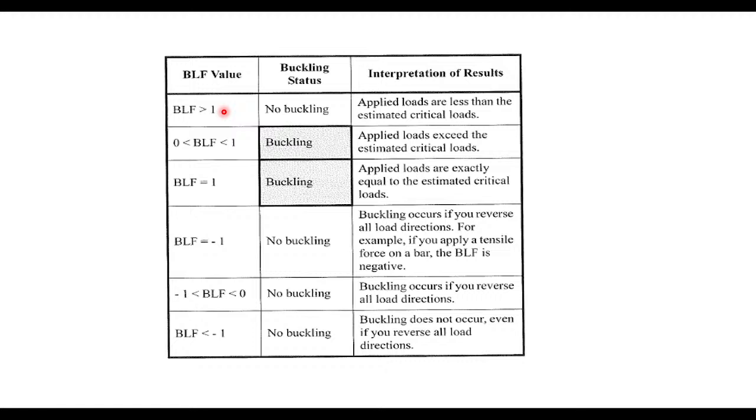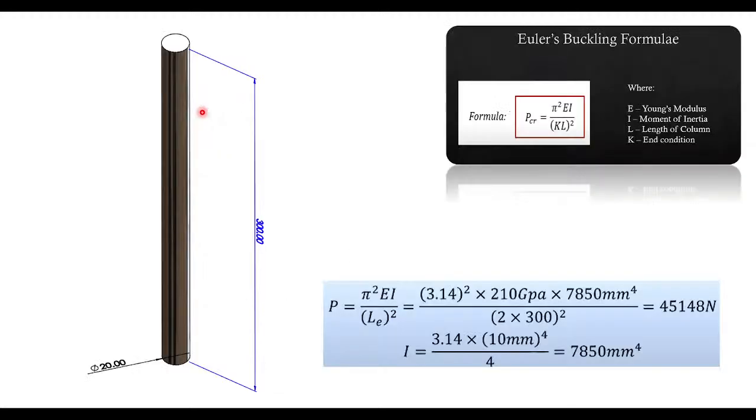We don't know, so we need to consider that. You need to ask what the buckling load factor standard is for this model. If they say it is 1, consider that. If they say some other value, please try to take that into account. Okay. Next, we'll consider this example.